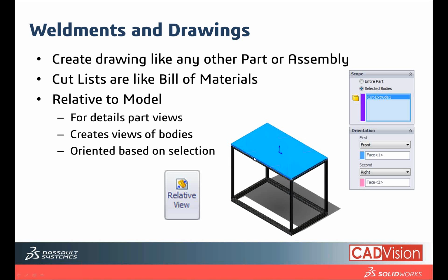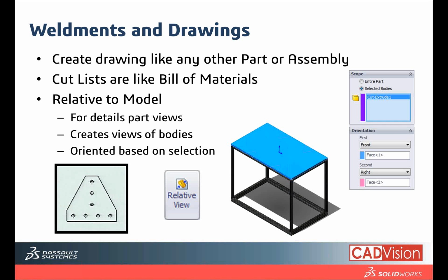Of course, if you are unable to click on that particular surface, plane, or face that you want, always right click and select others. Use the select others option to select what you want. It does not need to hide this particular flat plate in order for you to select this surface. You can always use right click and then select others.